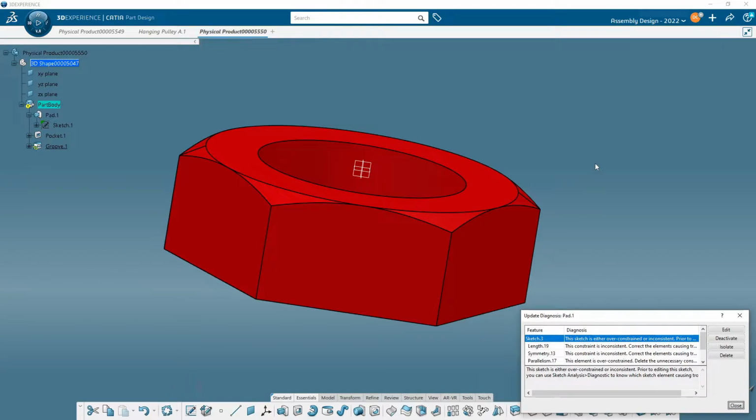So what are we going to do with this? What's happening? Now let me tell you a story also about why it is red. It's red, people would say, because it's an error. And that would be slightly incorrect, okay? If you look through your preferences, this is all CATIA, going back 20 years. Red means update. On older computers, if you would make a change, you might see it flash red for just a fraction of a second, and then it would be the typical grayish bluish color. That red is CATIA trying to calculate the numbers and rebuild the model, right? And so until that happens, it turns red.